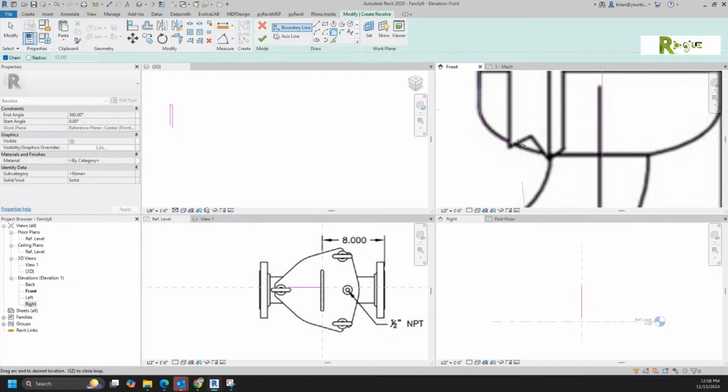If you go like this, what's going to happen is you won't get that extra line at the top that you need. It'll sort of disappear and look a little bit goofy. So my recommendation is you go with a 3-point and you don't go to where it snaps to that tangent point. You go just shy of that. It's going to give me a line around there. And I could close out my line, trim this up.